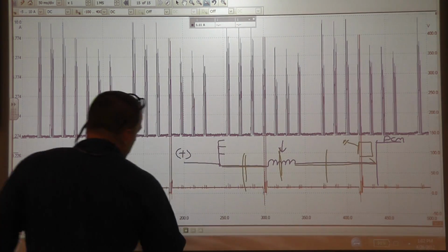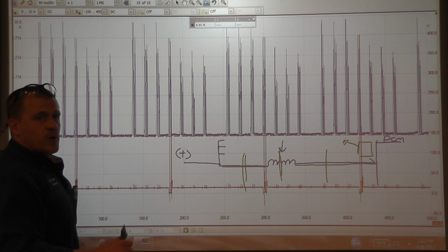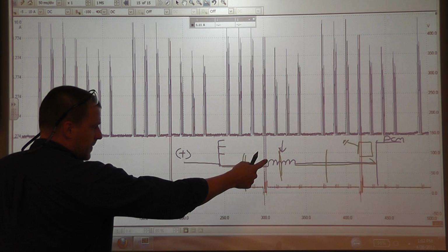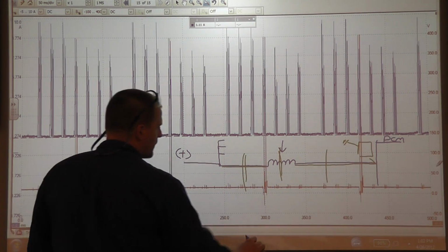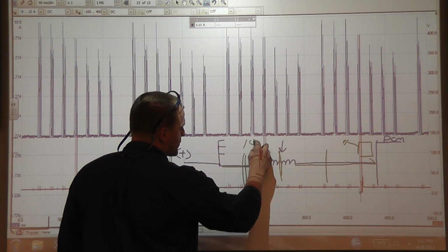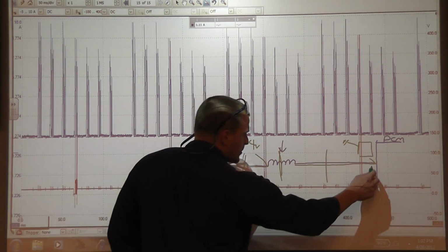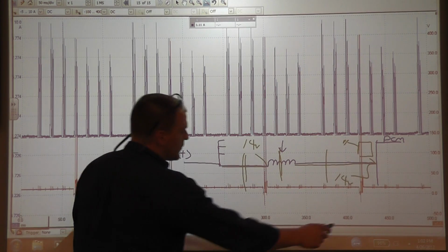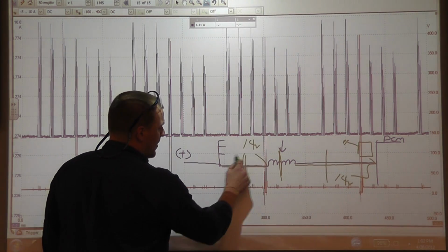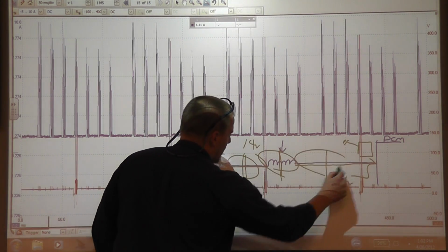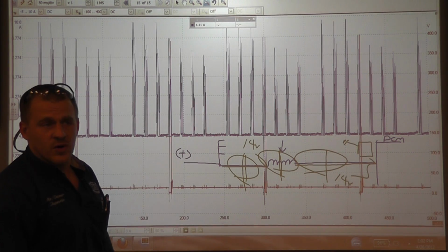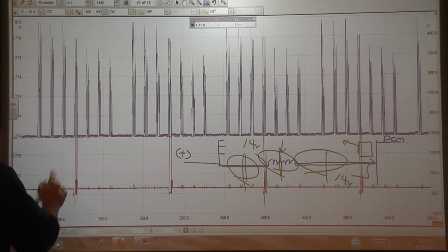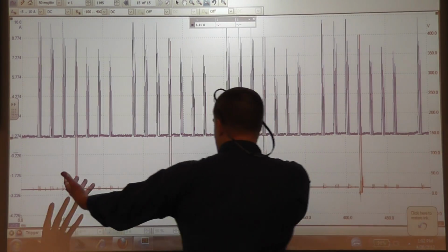Okay, so a little bit of electrical theory: if this circuit is off on this design, what are we going to see? What kind of voltage? Our feed voltage engine running is going to be 14. What are we going to see all the way at the computer with the circuit off? We want to see 14 volts. If you see 14 volts at that wire, it's all good. Okay? The way this circuit should work, take this known good picture.